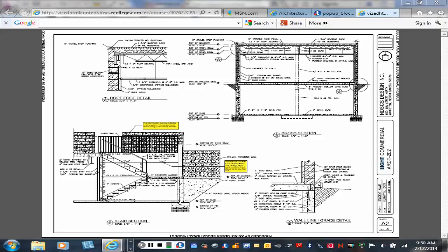The steel beam then, between our bar joists, we're going to try to keep those at roughly a 12-inch depth of a steel beam. And we'll talk more about that later. But I think, again, as long as we don't get over, I'll say, a 30-foot span, we should be able to get by with a W12 by, it could be a W12 by 20 or it could be a W12 by 60. It just is going to be in that 12 range.